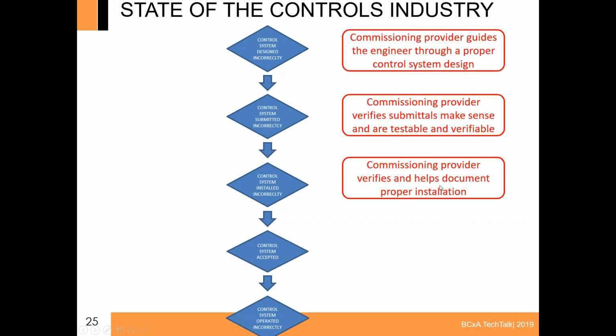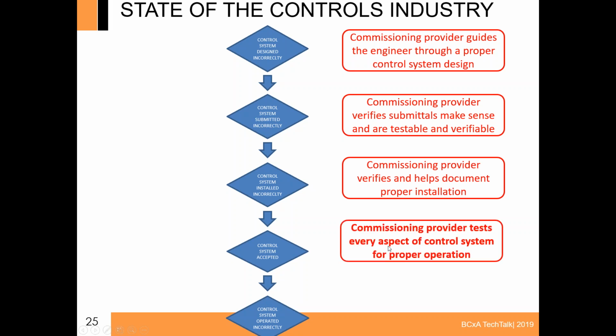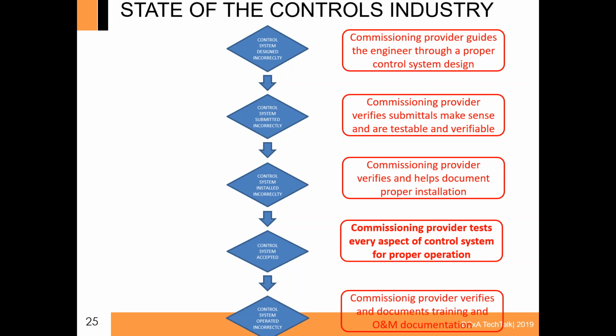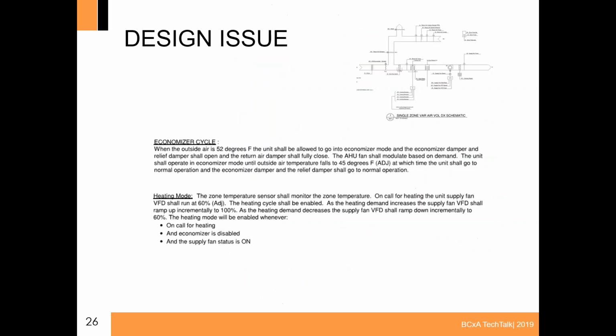Then we verify and document proper installation. Most important thing, we test every aspect of the control system: the point-to-points, the loops, the tuning, the software functions, the graphics, the alarms, and the trends. And then we make sure that proper training and documentation occurs so they can operate it.